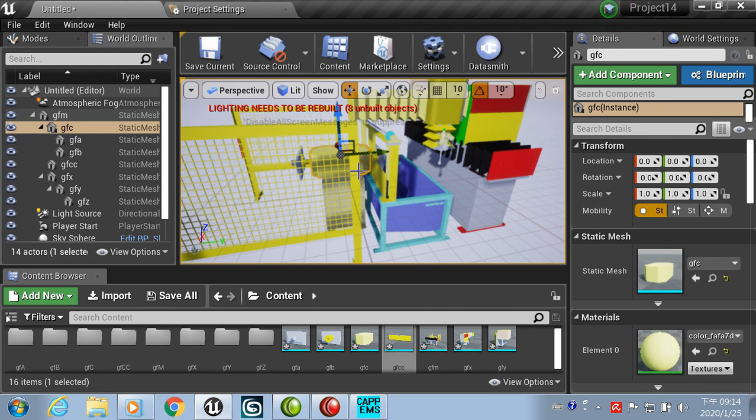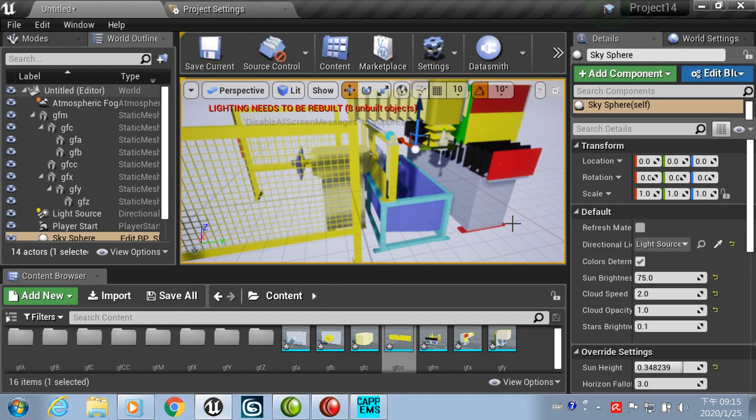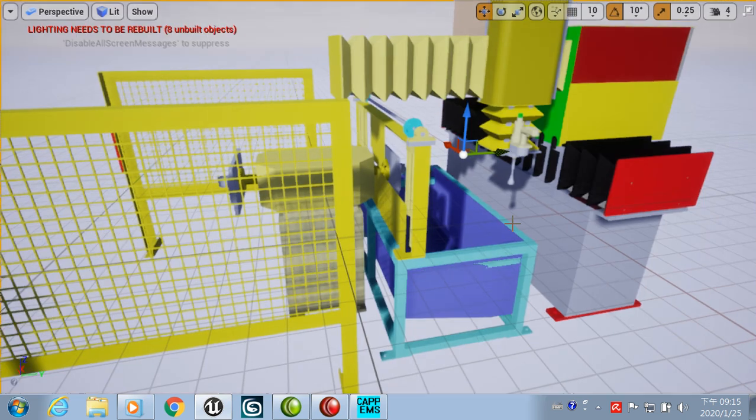The C moves, the AB will follow, but the foundation does not move. Right now in here showing the translation coordinates. For rotation we have to pick this one. Before picking this one, we enlarge the viewport by pressing F11, and put the cursor on top of C. Okay, this is the pivot point of C. For rotation, we have to choose this function.